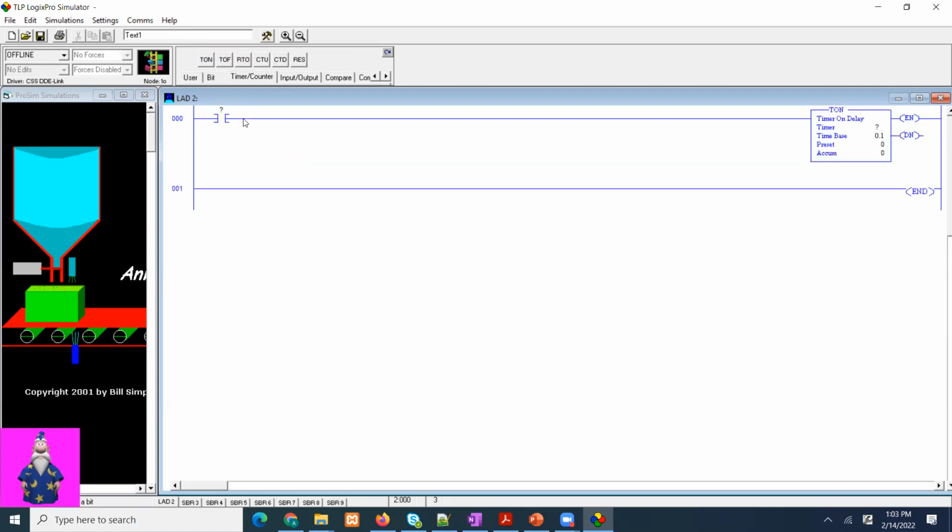We're going to first look at timer on, yeah? And then we are going to say this is T4:0. Okay, T4:0. We're going to say count for 5. Let's make it 50, so it is 5 seconds. Yeah. And this guy would be I:1/0.